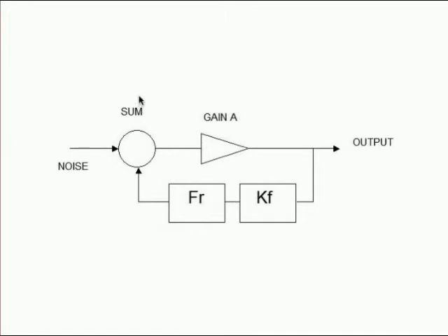What we're actually analysing is this block here, which takes broadband noise and filters it with a very narrow filter such that we produce a narrow output spectrum. So the output spectrum is very narrow, as we know the output spectrum of an oscillator is, but we're suggesting it is nothing more than filtered broadband noise.